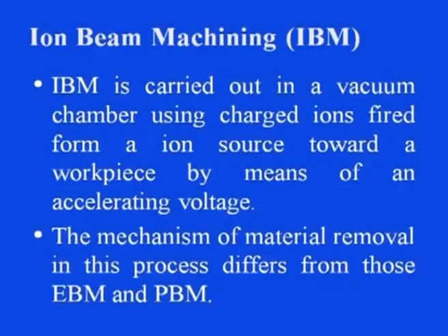Plasma beam machining is used to cut grooves in stainless steel. The process is also recommended for parts that have subsequent welding operations. Underwater numerical control plasma is also used with higher machining accuracies of plus minus 0.2 millimeter in 9 meter at a lower cutting speed. Now, let us move on to another precision beam machining technique, that is ion beam machining.